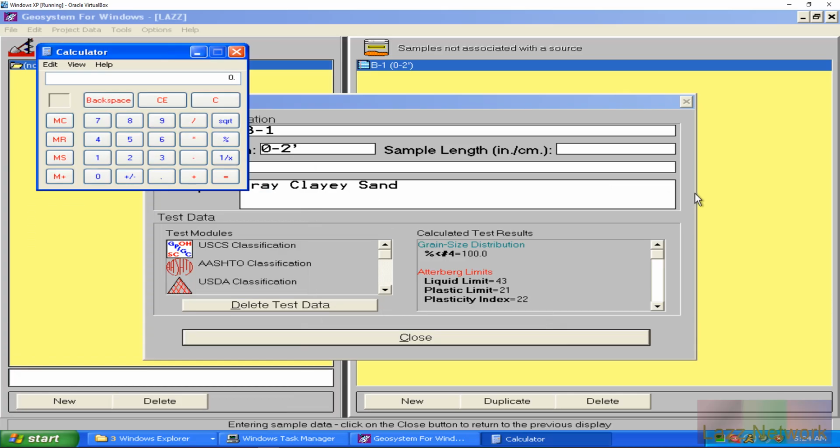So if we have 149.31 minus our tare weight, that would be 50.76. This is our material of soil that's been air dried before. Let's put that in memory real quick. So 9.01 divided by that, times 100, minus 100. Okay, so we have about 90.9% passing. Oh cool, remembered that too. That's good. So let's do 90.9.